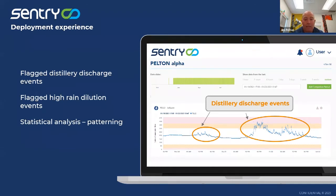And then in hindsight, the idea that a RAS pit is pretty low on biological activity makes sense. All your bugs are starving, there's no more nutrients left. So in hindsight that makes a lot of sense as to why we weren't seeing very much data in a RAS pit. And we started seeing almost immediately both toxic shocks and the impact of rain. Once we had some trend lines, you start to see the impact of all the different events that Frankfurt was experiencing.